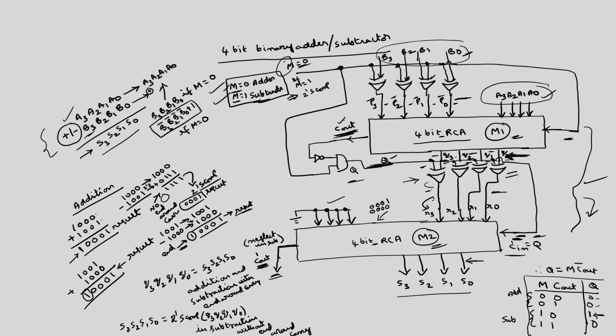And this C out we have to define as a wire, and after this NOT gate you call the output T, which you also define as a wire. So this also you have to make as a ground. Let us take this one as G3, G2, G1, G0.